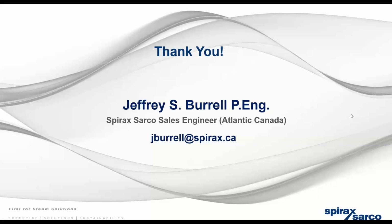It's another half-hour presentation on its own. Agreed. Excess surface area, stall, et cetera. But if we design, and it's pretty simple in my mind, every system out there on a process site is going into stall. So if we assume that, we just need to design for that, and it's going to go into vacuum. So it's very simple. Just design for that, and then you'll never have a water hammer issue in a process heat exchanger.